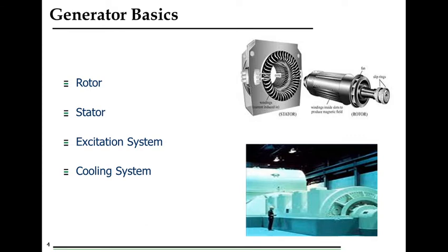Now, why is the armature winding in stator? This is a general question. To answer this, at a high voltage, it is easier to insulate the stationary winding, which may be as high as 25 kV or even more in some cases. The generated high voltage output can be directly taken out from the stationary part, whereas for a rotating armature there will be large brush contact voltage drop. Also, the sparking at the brush surface will be a problem to look after.